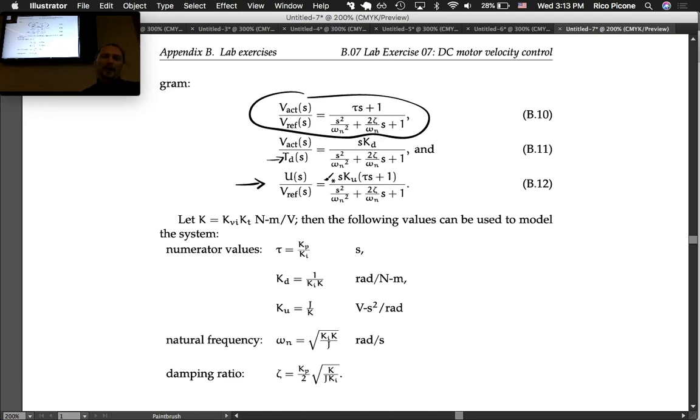So you have a transfer function that'll tell you, for instance, if you have a step input in your reference, what your response looks like for the voltage out of the controller. So this is what you would investigate to find out: am I saturating my control? Do I have more space to be more aggressive with control, potentially?